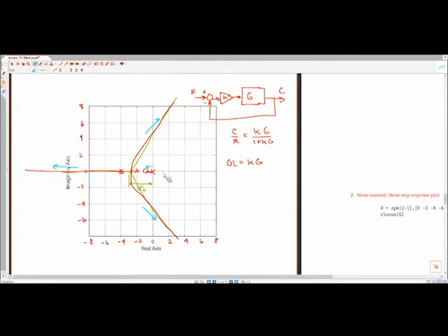Okay, so in terms of things that we have to worry about here, we don't have to worry about the closed loop pole here going unstable. It's going to terminate at the 0. We do have to worry about these closed loop poles associated with these branches here. All right, so if k gets to be too large, our system will go unstable by this analysis. Any questions on that general kind of math concept that we have here? Okay.